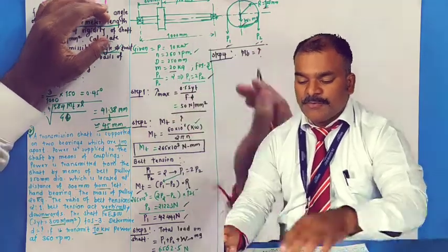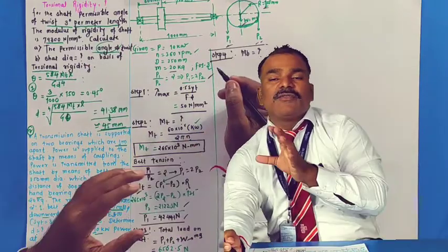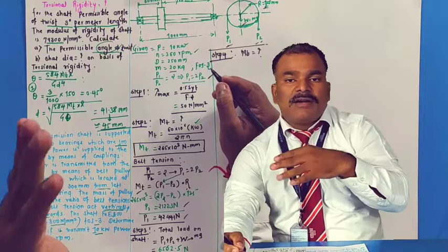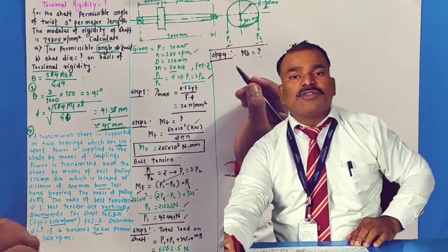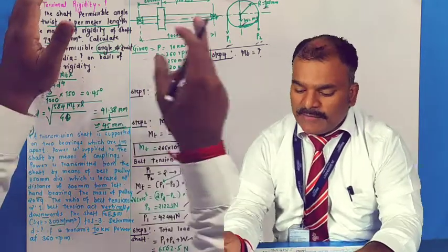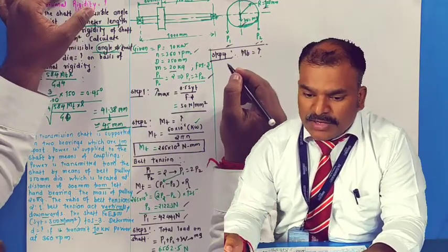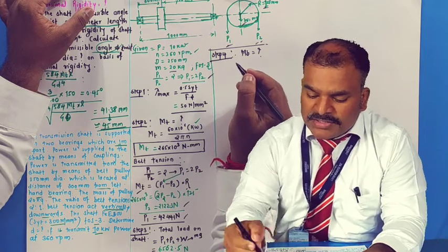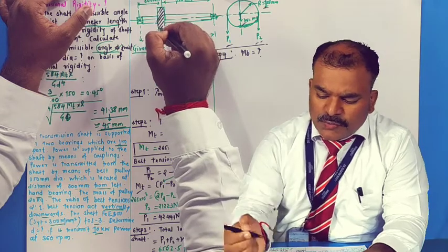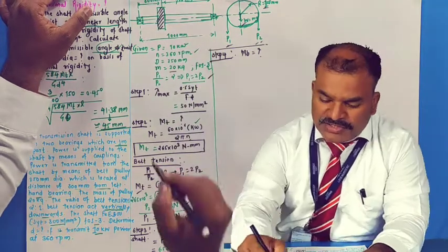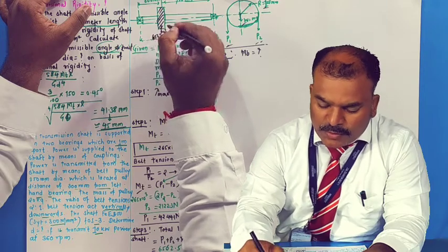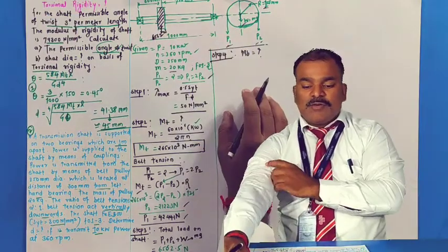See the structure carefully. Now here the rule of bending moment is very important. In the numerical, maximum hurdles come at the bending moment calculation, because the remaining things are common. So for bending moment, you can see the structure I have drawn carefully. This is the pulley, correct? So force is acting, total force 6562 Newton, correct? Total force. Now I need to calculate the bending moment.